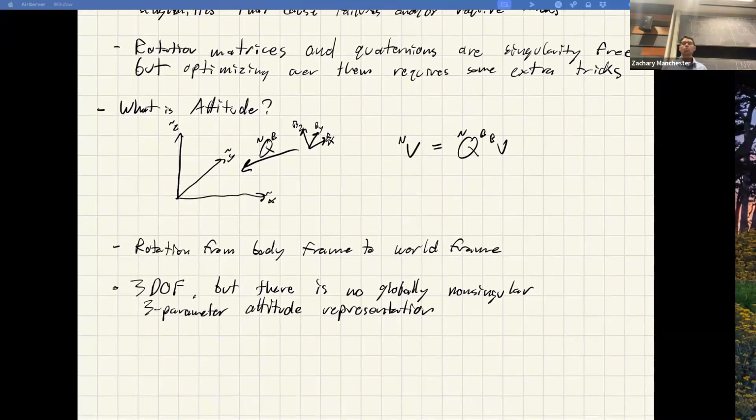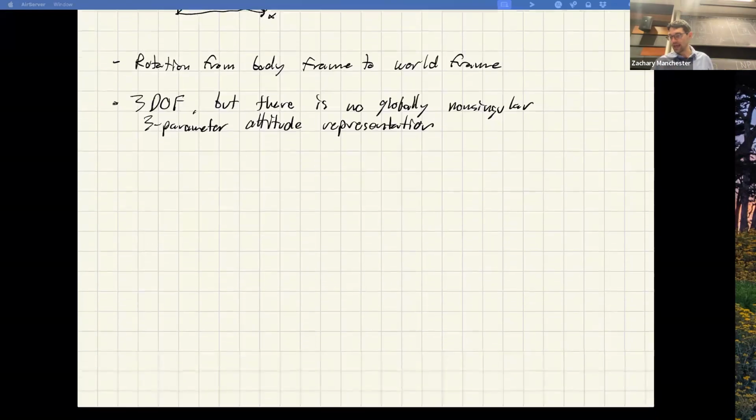What it means is that if you were to write down the Jacobian mapping Euler angles into anything else, for example, converting the Euler angles to a rotation matrix, or writing down the forward kinematics of my robot, mapping literally anything, the Jacobian associated with mapping Euler angles into something else becomes singular. That's what it means. Basically, it means they blow up somewhere. We'll clarify this as we go. We've got to write some more math down to give you a tight definition. Okay, cool. So that's that.